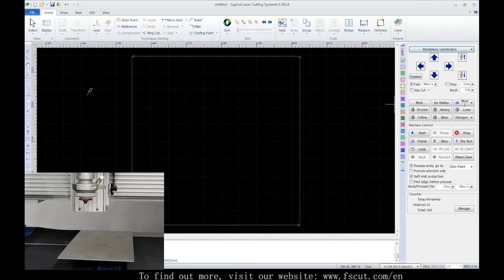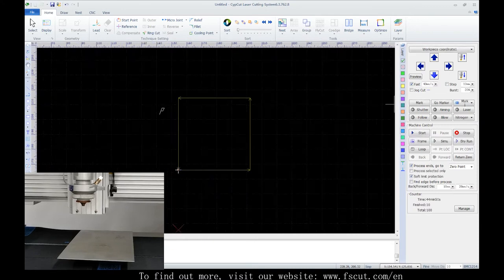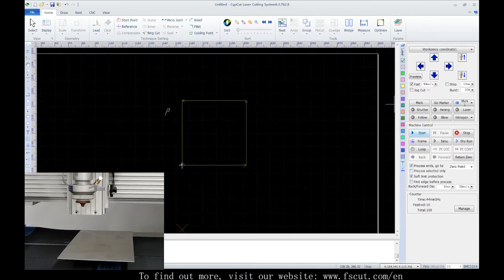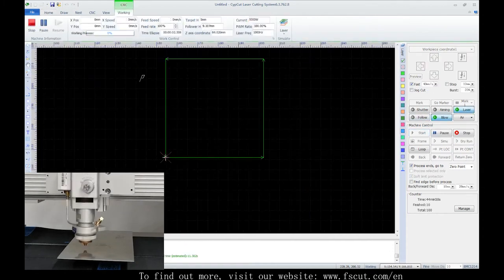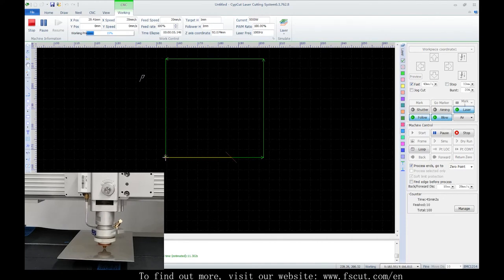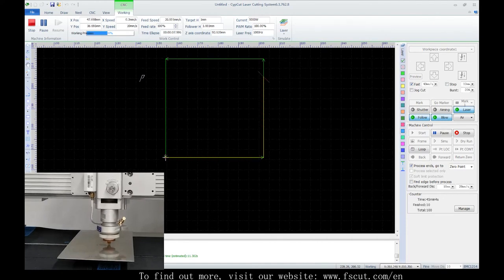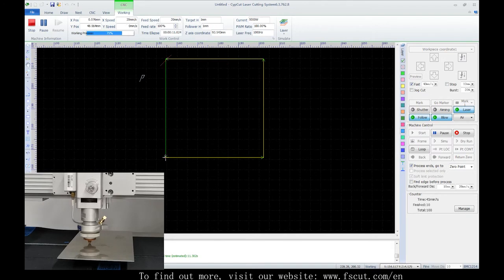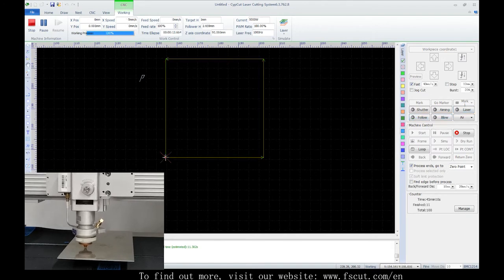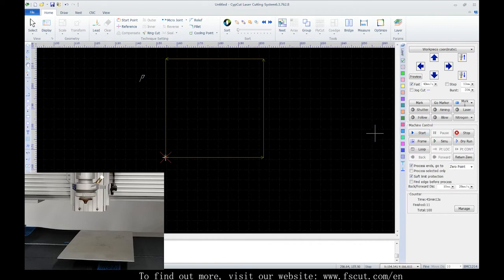During the process, if the cutting head was moved to another position, so long as it gets an instruction to start, it will return to the graphic next to the defined 0-point, and then start cutting. This coordinate is used in mass production scenarios where a large quantity of plates of the same size are placed in the same position on the machine bed, which also requires a 0-point of fixed position.